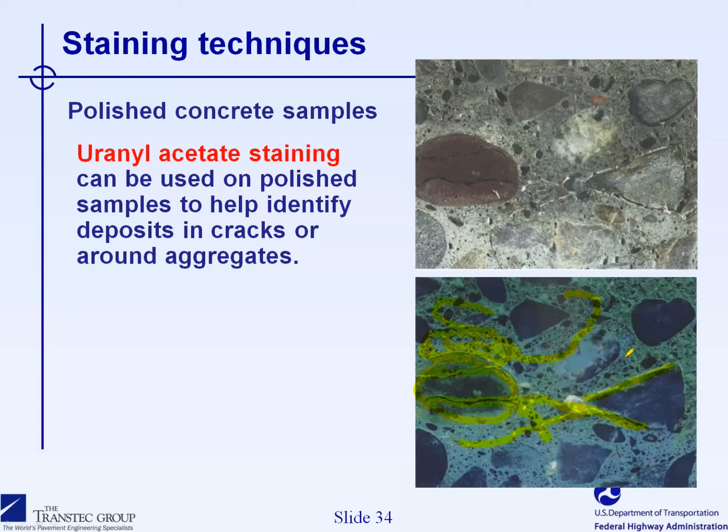Okay, and as a follow-up to that, if the concrete is designed with expanded shale, clay, or slate lightweight aggregates, will the voids in these aggregates provide a space for the ASR gel to go, thereby protecting the air entrainment voids? As I just said, based on the evaluation of a fairly large number of concrete specimens, the gel is generally limited to the cracks and is not necessarily oozing out of the reactive particle.